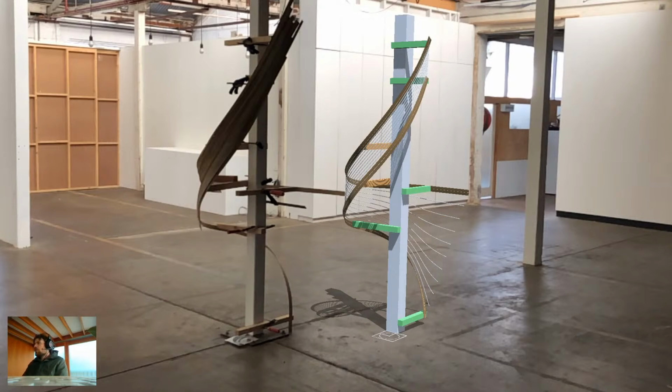The main idea here is, typically with steam bending, it's an incredibly time-consuming, difficult, expensive process, because you have to fabricate a mold for each part that you want to bend in order to try to minimize the springback and maintain a predictability of the bent timber. Whereas we were hoping that, much like with the pipe bending, by having a holographic representation of what the finished part would be, we would be able to continually adjust the timber while bending it to make sure that it closely matched the holographic representation, regardless of whether there was springback or unpredictable behavior of the material.